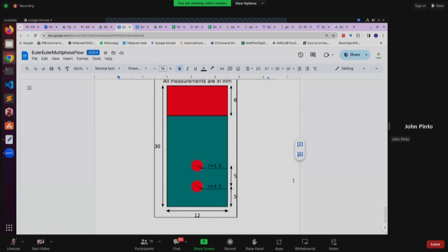The result shown in ParaView is similar to the VOF approach, right? Yes. If you keep reducing the diameter of the dispersed phase, then this bubble, when it is going up, will kind of diffuse. It will not remain intact as one bubble. That is also something that you can try a little later. But when we are simulating the fluidized bed next, you will be able to see that.